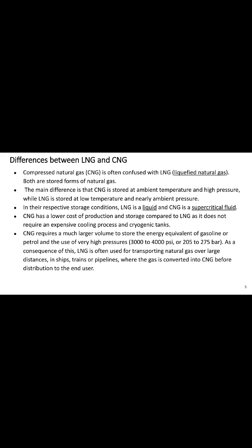CNG has a lower cost of production and storage compared to LNG as it does not require an expensive cooling process and cryogenic tanks. CNG requires a much larger volume to store the energy equivalent of gasoline or petrol and the use of very high pressure, about 3000 to 4000 psi or 205 to 275 bar.